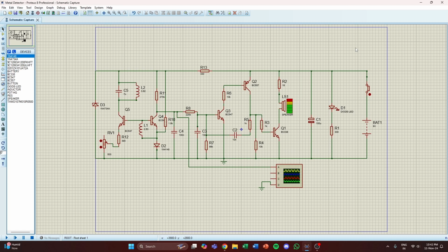This happens very quickly, and during this time, the 10N capacitor starts to charge. Current flows through the base emitter junction of the third transistor. As the capacitor charges, it develops a voltage across it. This causes the charging current to reduce. The third transistor gradually turns off, and this turns the fourth transistor off slightly. The voltage on the collector of the fourth transistor drops, and the voltage across the 10N capacitor causes the third transistor to turn off completely. This turns off the fourth transistor, and now both are fully turned off. The 10N discharges through the 56K, and the cycle repeats.